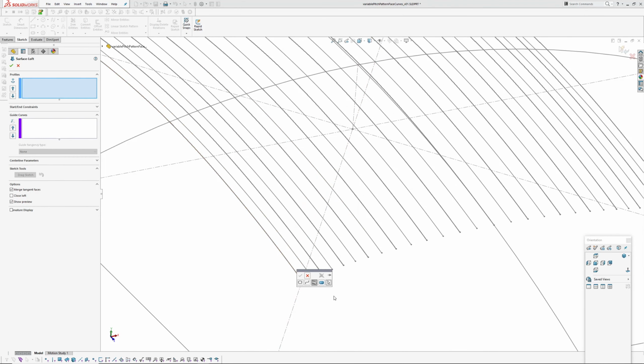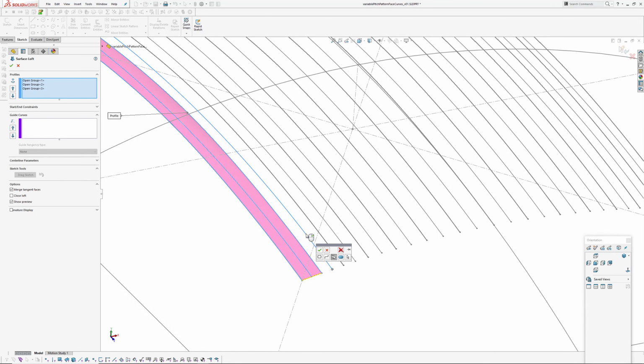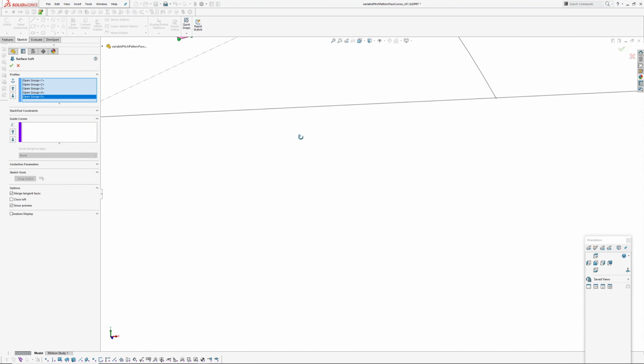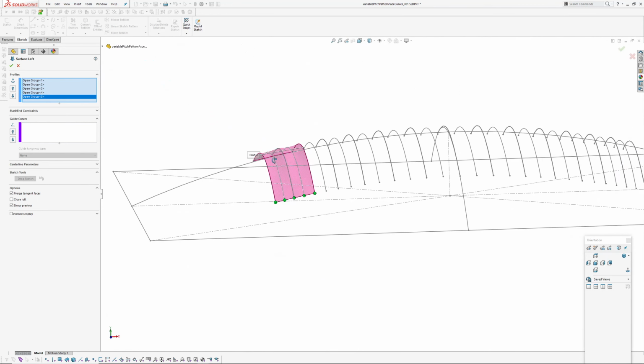see it's popped up with the selection manager because it knows that's an entity within a 3D sketch which also has all these other curves. So if you pick one and then push enter, you can move on to the next one. Whoops. And so on, and that's how I built the loft there.